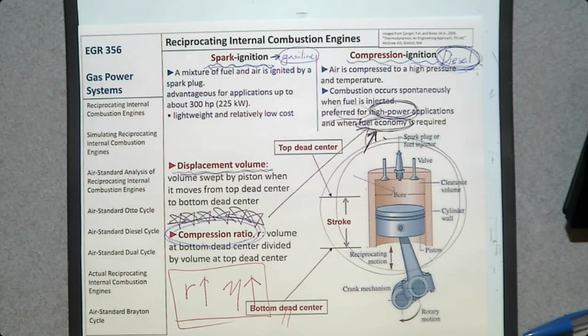But when you use a diesel engine, because of the compression ratio and fuel efficiency, you want to increase pressure as much as you can. Then what is the problem when we have combustion at extremely high pressure? Nitrogen gas is usually called an inert gas. It doesn't react in general, but at high pressure, it reacts.